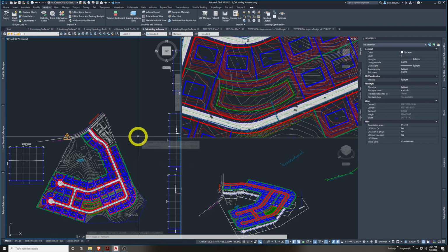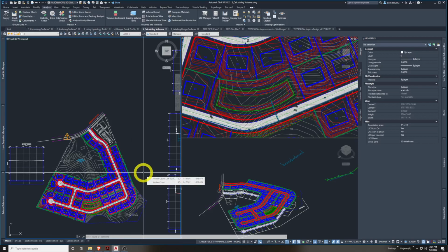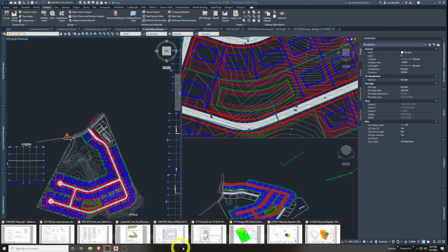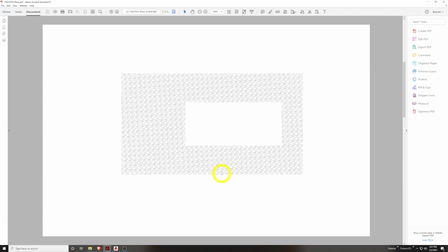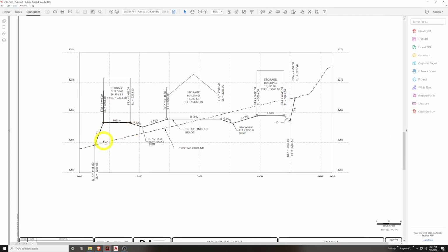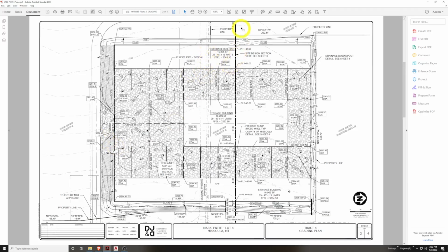So if you go to page 377, it produces what you call a cut and fill. So cut is scenarios where what you are designing needs to cut into the existing earth, and fill is scenarios where what you're designing needs to go down to or embank on top of the existing earth in a lot of ways. And a lot of times when I was showing you this picture here, for example, on Mark White, I was showing kind of this is a cross section of the whole site. It crossed it one slice. So this is kind of like, here it is right here. It's basically this phantom line.